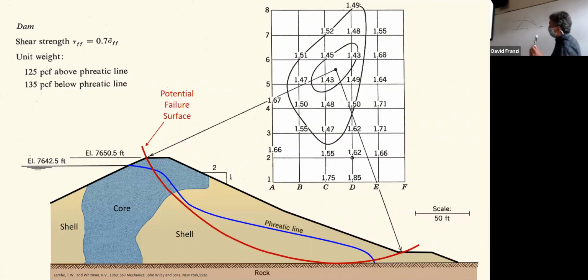Now, I don't know if you remember the talus slope that we saw in Iceland, where it had started to slide, and the Icelandic Department of Transportation had done some things to clear that slope. Well, what's going to happen there is that slide is going to continue to cut back until, again, it reaches that angle where the factors of safety, the forces driving motion and resisting motion, are balanced again. And that's all you're doing, is just balancing forces all this time.